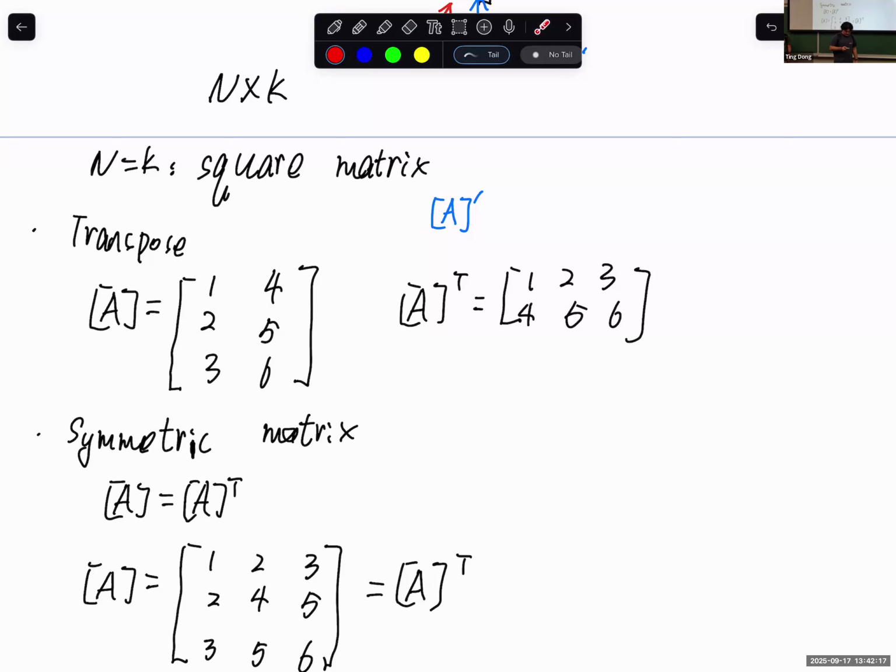And now since you calculate all the nodal displacements, so let's say 0, 0, something, something. You have 4 points, you use straight lines. It becomes a displacement field. Makes sense or not? Makes sense. FEA is really calculating the nodal displacement. Let's say U1 is 0, U2 something, U4 something. I have no idea what that graph means.